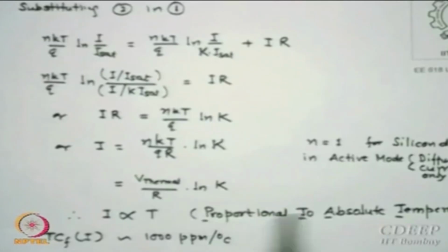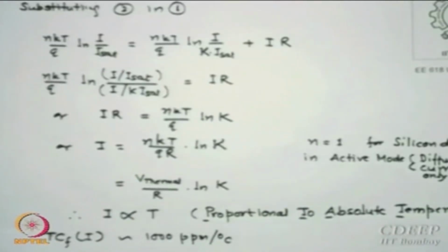So this current source is called proportional to absolute temperature. What will be the advantage of this? Not as a current source, but what is the importance, the advantage of this? Where do you think you can use this? A sensor, a thermal sensor. You have to monitor temperature, so characterize once, and whatever current you monitor or voltage drop you take, proportional to that you can display the temperature. Is that clear? So this is not useful as a current source, but it is useful as a temperature sensor. Is that correct? That's why the word came, proportional to absolute temperature. Okay, is that clear? Don't ask me what its TCF is. Actually we do not have to take TCF for this. We are not using this as a good current source.